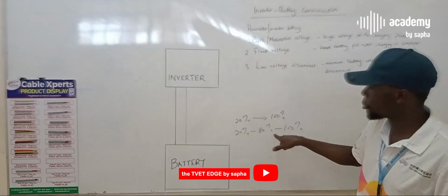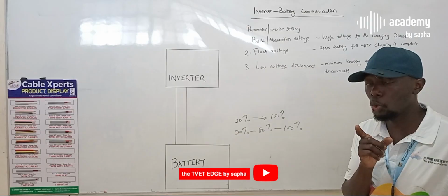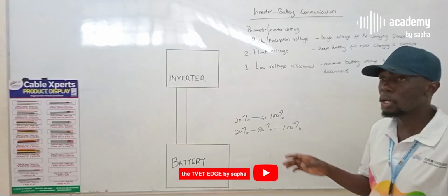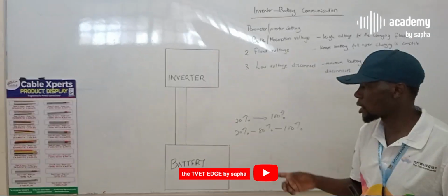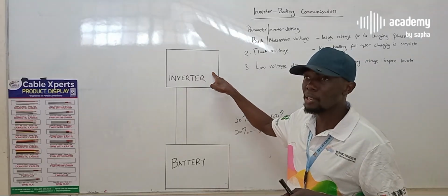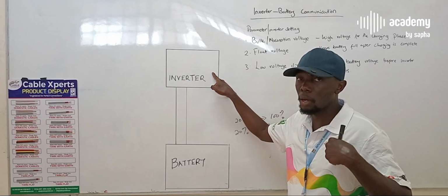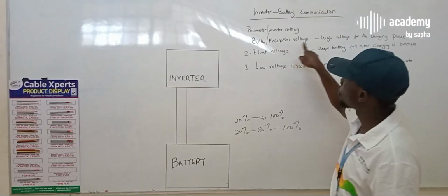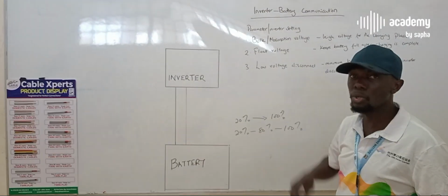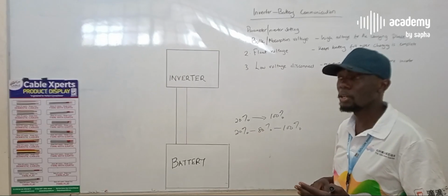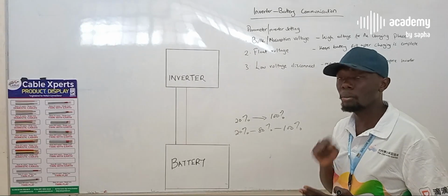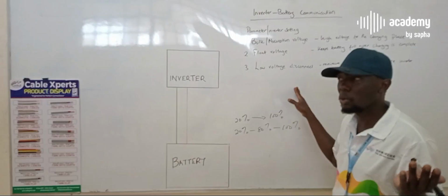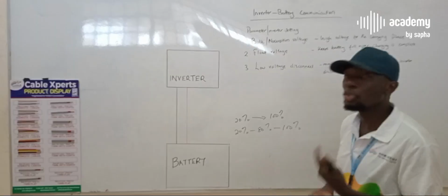And you can also pre-program this to happen even using the daily sun hour behaviors. So some inverters can decide this to happen pre-programmed, or they can allow you to program that setting so that this bulk or absorption voltage phase happens between, let's say, 9 a.m. and 1 p.m. And then from 1 p.m., whatever state the battery is, you shift.